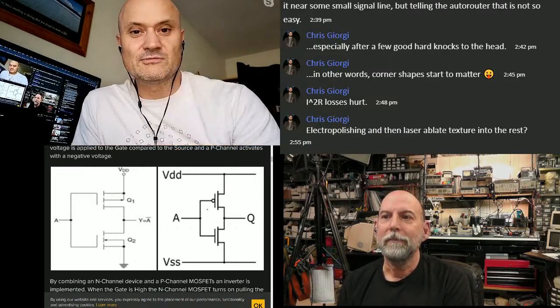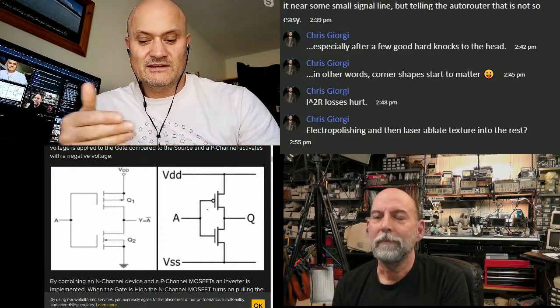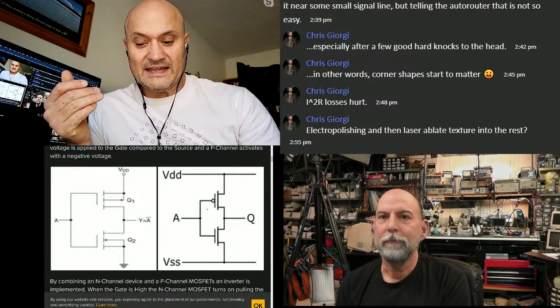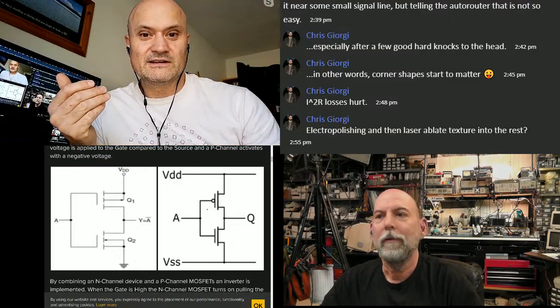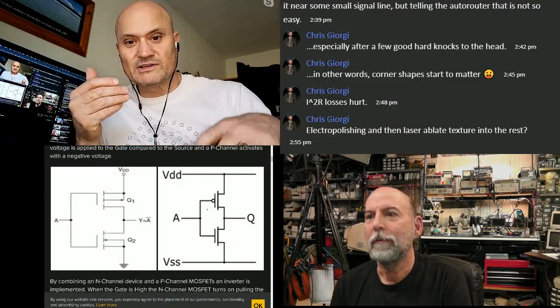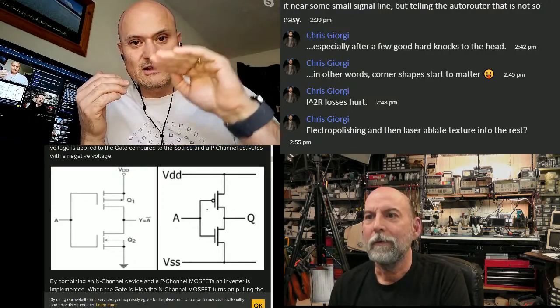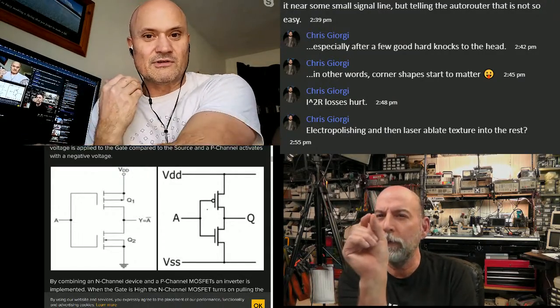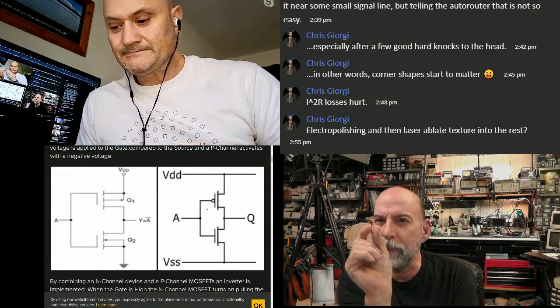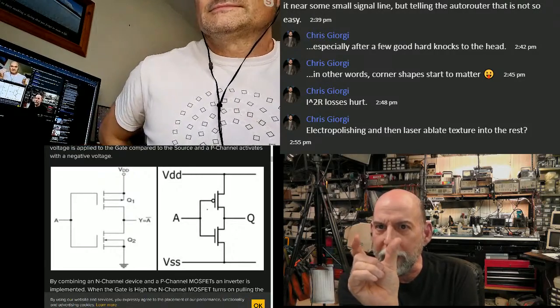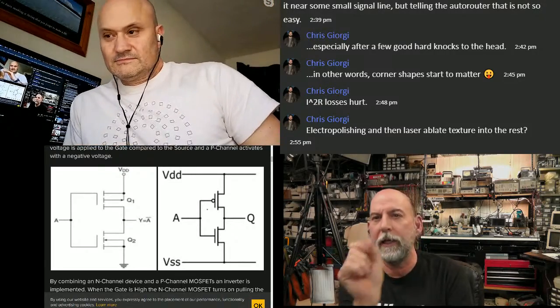So, traditionally designers put a layer stack indicator in the board, on the edge of the board or in their coupon, and they have the layer numbers etched into each layer, and you can tell if they're in the right order, or you can even score the side of it and polish it and look at it sideways and see where the copper is, and it should look like a stair step. So you make layer 1 have a little bit of copper, layer 2 has more copper, 3 has more, and 4, so you can tell by the length of the copper.